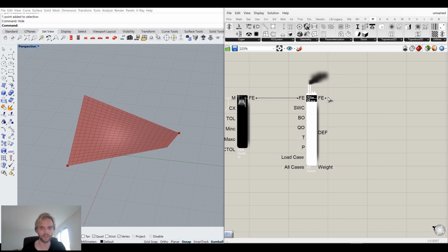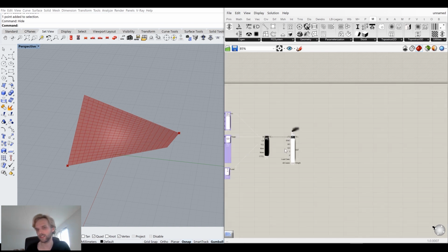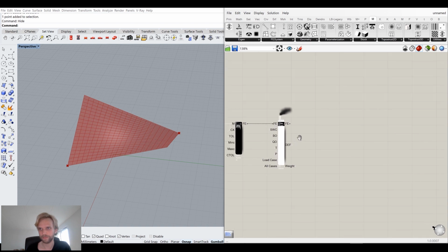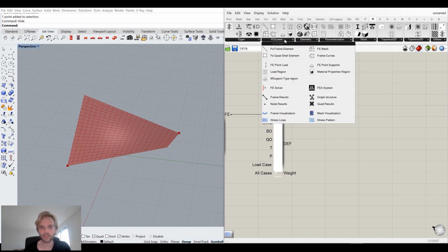And it does it automatically, so now it's calculated, right? We have the calculated FE model, we have the maximum deflection, meaning how much it bends, and it's a very low number, only 5 millimeters, and it has its own weight, right? And the weight is, I don't know how the weight is calculated. I guess it's just steel multiplied by volume, right? Yeah. Anyway, steel density multiplied by volume. Anyway, we have the calculated system output here.